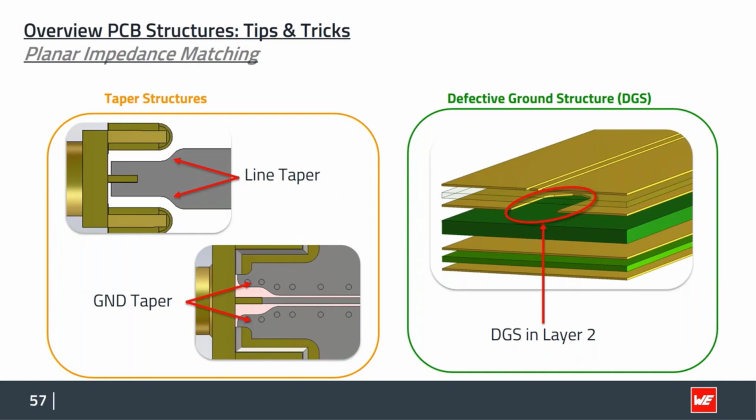If you look at the line taper on the top left, basically in the open area we have our 50 ohm line crossing the PCB, optimized for the height, for the epsilon R and so on. But in the connector, we have ground here, ground here, and the signal here. So this behaves more or less like a coplanar waveguide in the entrance area of the transmission.